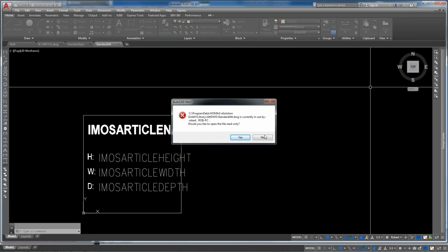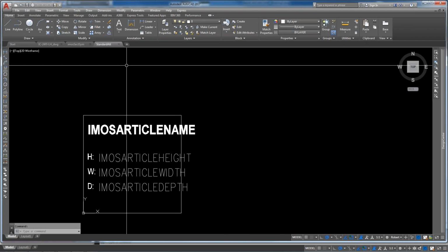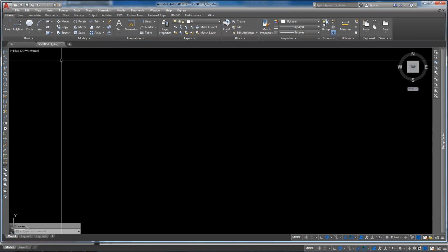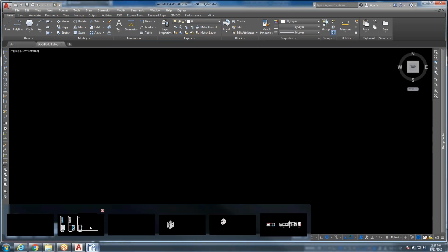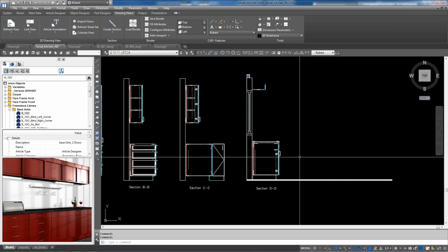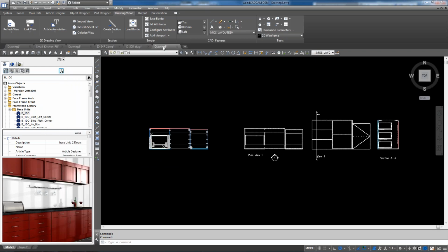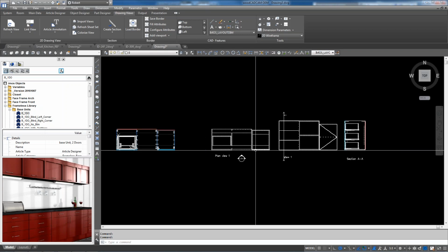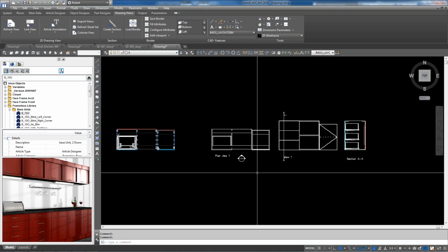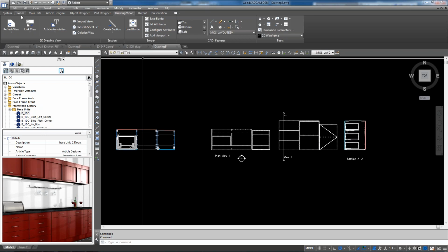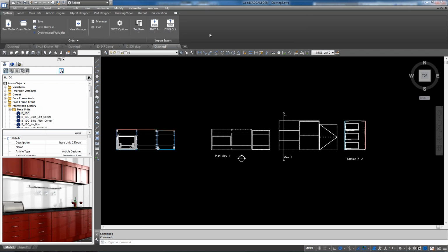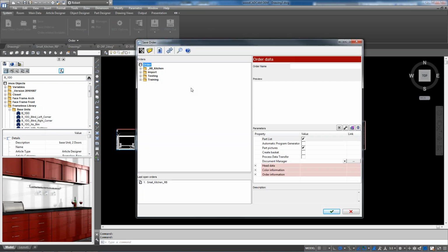Other questions? All right, let's go back to the drawing where we had the two cabinets in it, when we just did that last drawing. It was drawing 3. All right, so let's say that we're ready to put this out to the shop. We want to go to the CNC, and you guys aren't set up on that yet, but I'm going to show you the process. It's fairly simple. So we're going to go to the System tab, Save Order As. In this case, he doesn't have the order saved, so he'll give it a name. Just call it CNC Test for now.